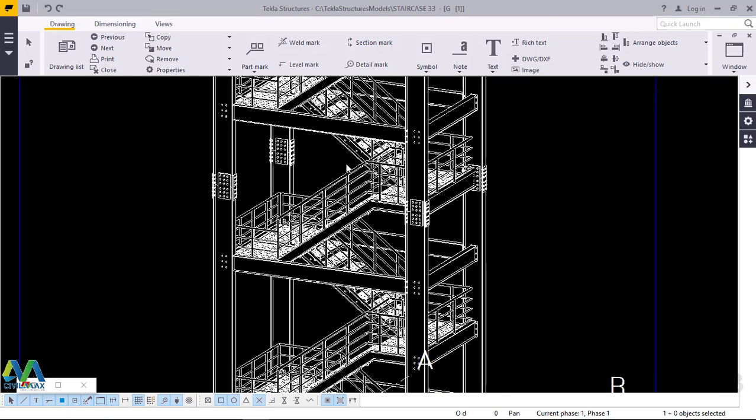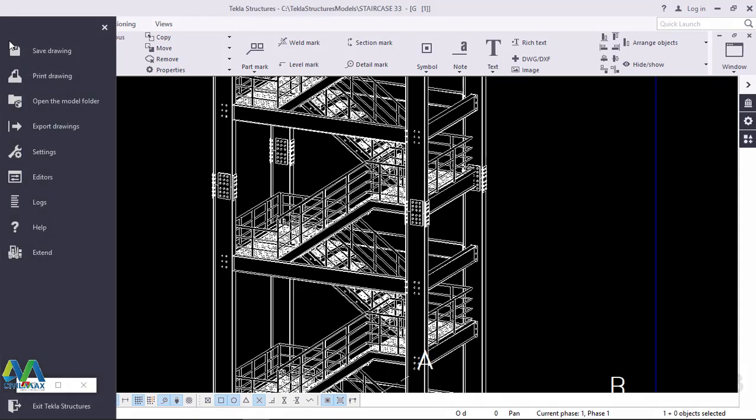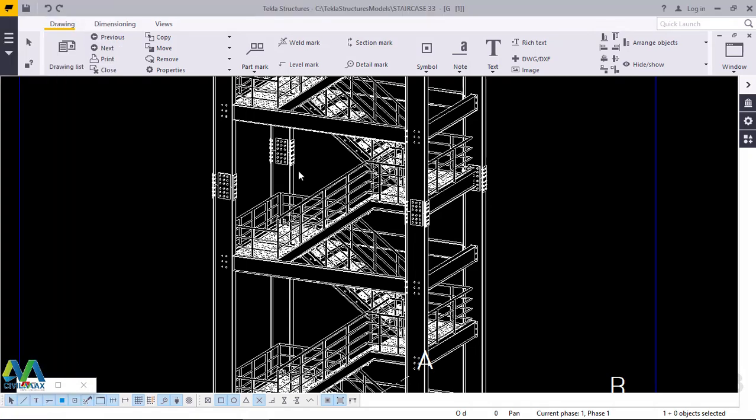To convert this to PDF format, just come to File here, then come straight to Print. Then you give it time to load. The moment it has loaded, you'll see the PDF dialog box come up, with instructions to follow, and you'll be able to create a copy of a PDF format for your drawing. We've given instruction that we are requesting a PDF drawing format, shareable to whoever doesn't have CAD software, and just give it time to load.